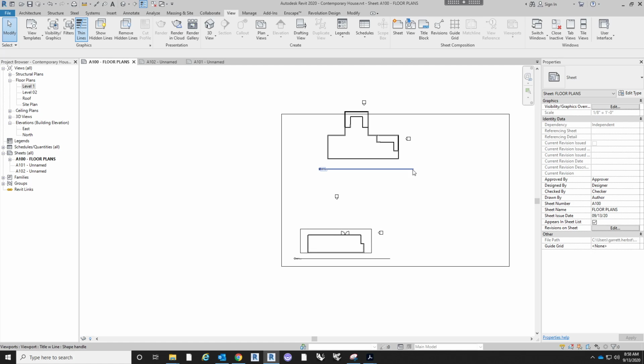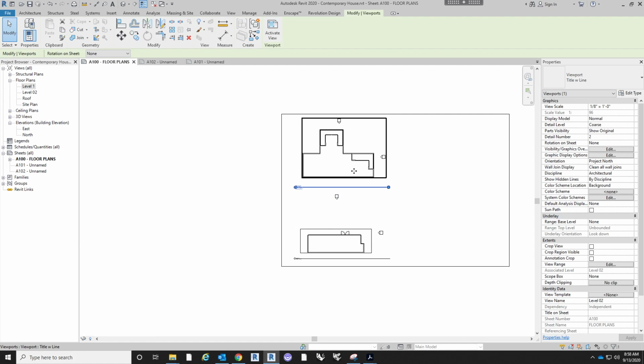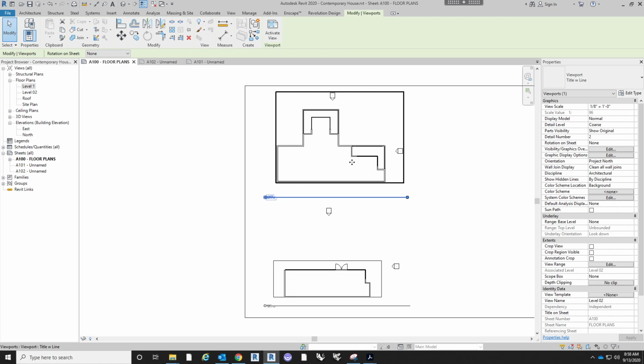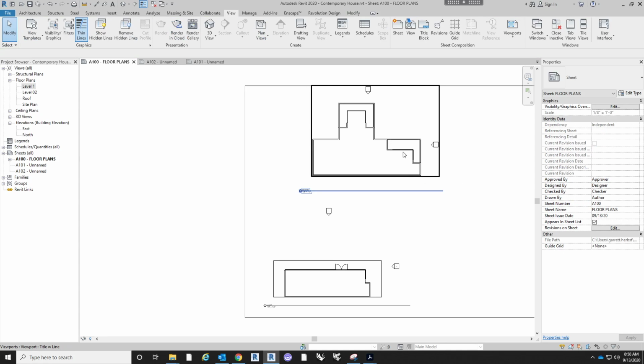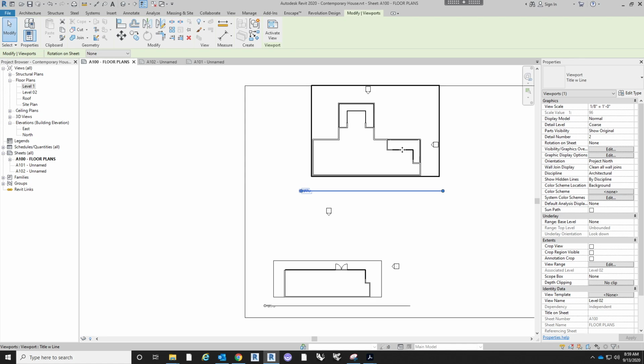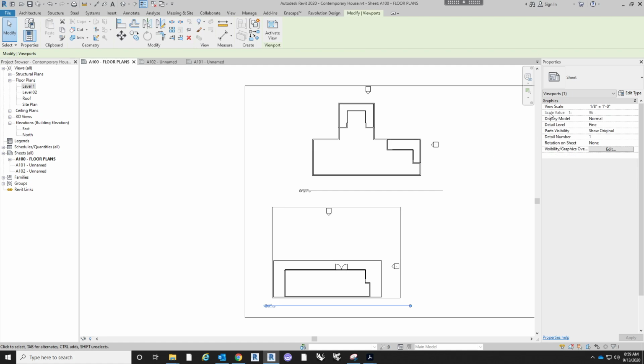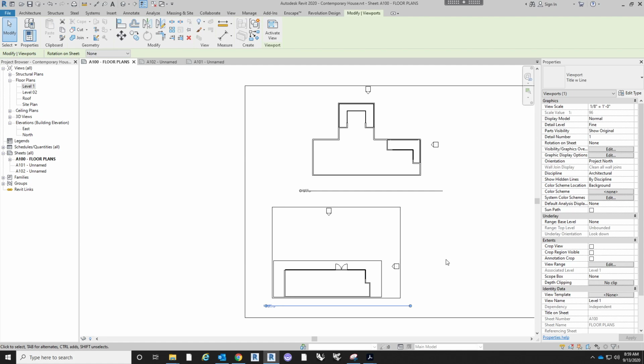All right. The other thing to consider, and I'll go through a scale change as well, because you guys need to know that. But before we do that, I want to show you how you can align drawings to each other. So if they are the same scale, which these two are, and to see what scale it is, all you gotta do is click on the drawing, go to the right hand side under the properties, and that first tab shows you the scale. Right now it's at 1/8 inch equals a foot. Same thing for this one, 1/8 of an inch equals a foot.